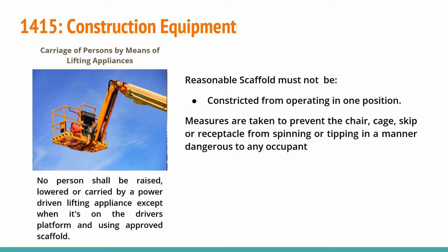Carriage of persons by means of lifting appliances. No person shall be raised by a power-driven lifting device without using an approved scaffold. Ensure the person's safety at all times. The person must not be constricted in operating in one position, and measures shall be taken to prevent accidents such as spinning, tipping, etc.